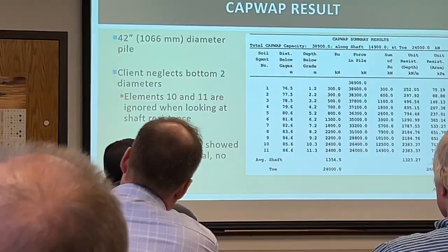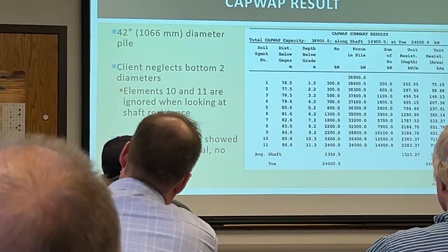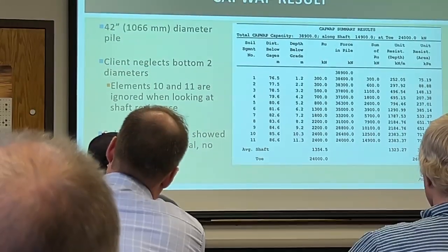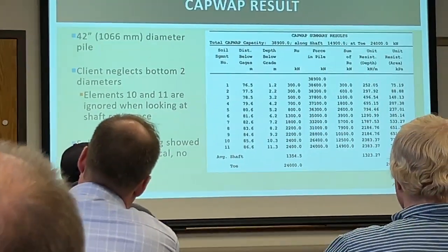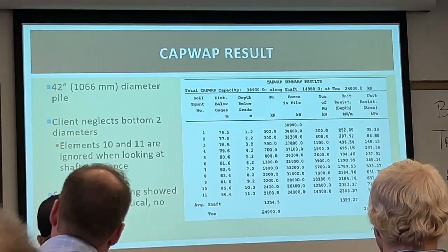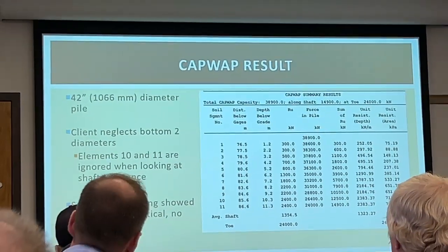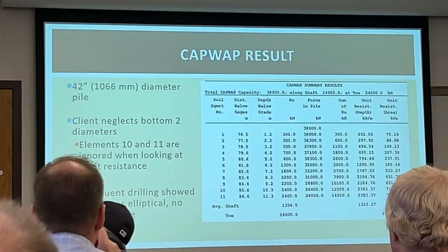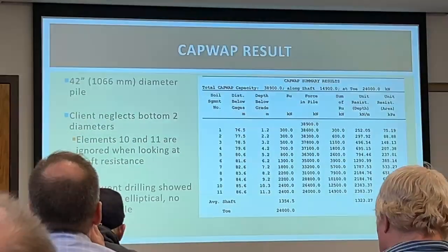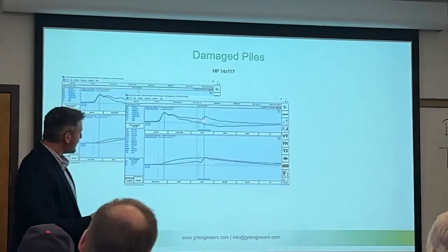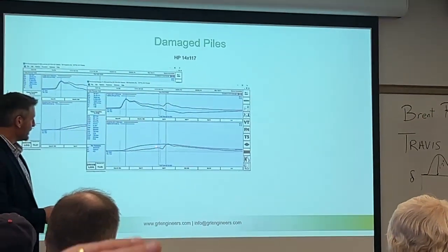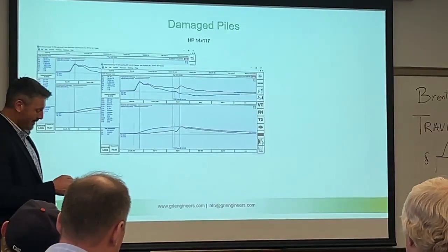And so sometimes if you are driving piles to rock, and I've seen it recently in Ohio, then deformations in the flanges of an H-pile are just something we can't pick up with the way that PDA works. If the pile gets shorter, that is, and gets crumpled up, that is something that we can find. So with that, we hit 245. You can see that much positive in the velocity. You can see the force dropping off there pretty clearly. Pretty pronounced break in your wave up prior to the toe.